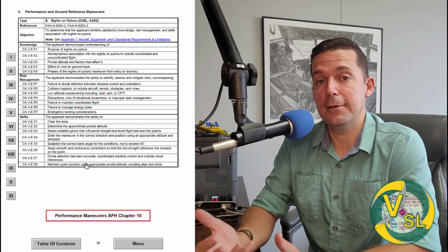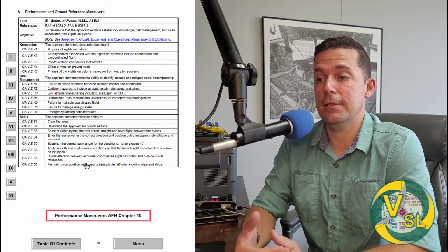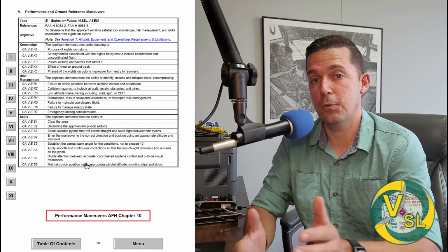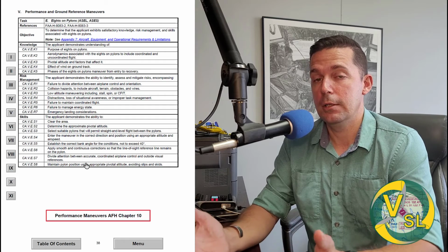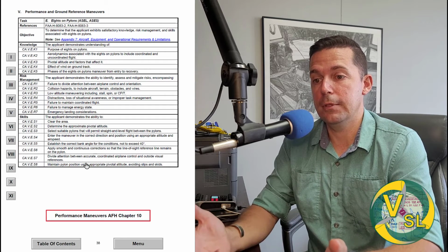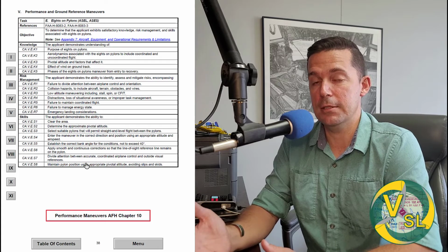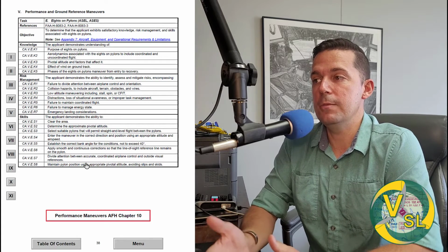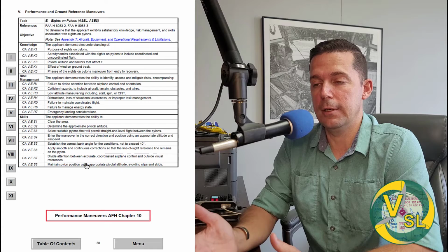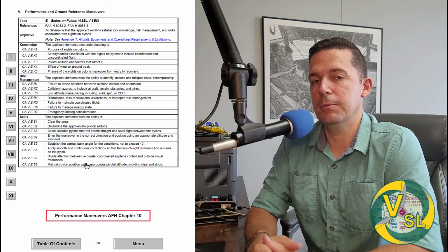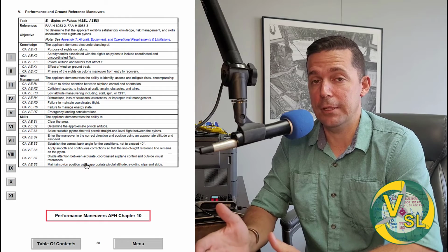What would probably be better is for you to have an idea, based on the area that we're going to be flying, which you know ahead of time, right? Before we go out to the airplane, the general altitude of the ground we're flying over, as far as MSL altitudes. So you should come up with an approximate pivotal altitude before we even get in the airplane.